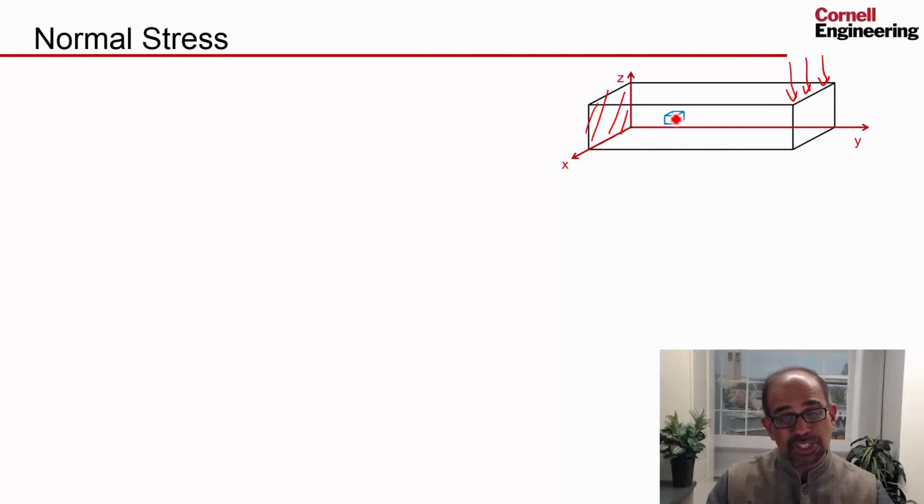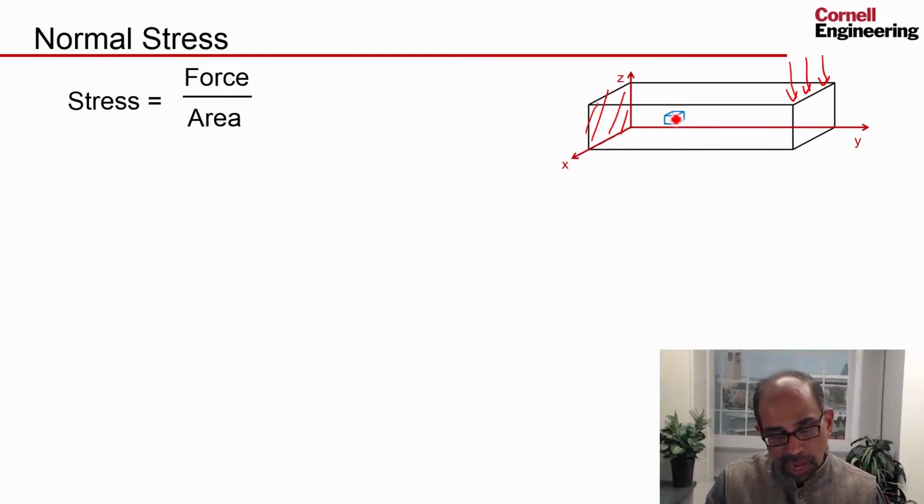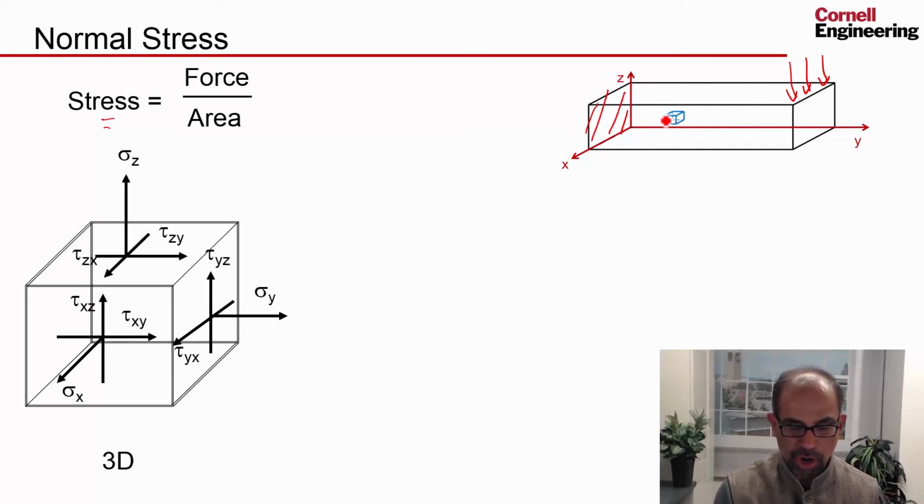Now we are looking at the forces on this little chunk of material, because this tiny chunk of material is going to be pulled or pushed by the material next to it on all the faces, and it's also going to be sheared. And in fact, I'm interested in the forces on the faces, but I look at it in terms of a stress, which is force per unit area, in the limit as the area of these faces goes to 0. And if I draw out the stresses on the faces, I'll get something like that.